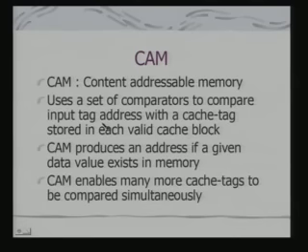The other way of looking into the cache, or increasing its efficiency, is to use what we call CAM, or content addressable cache memory. Now, in a way, CAM implements a fully associative cache. That means, without really mapping each location of the memory to one location in the cache, in an intelligent way, CAM implements almost a fully associative cache.